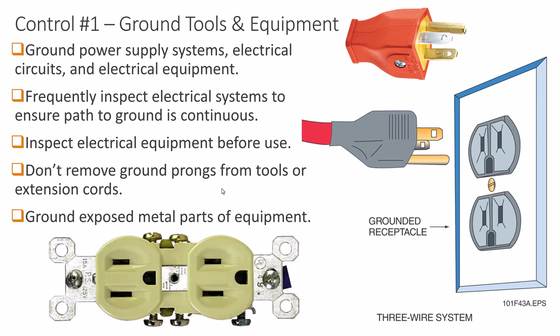You see on this electrical outlet here on the bottom, a real picture of one, how the hot wire is a smaller slot, the shorter of the slots, and the longer of the two slots is the neutral wire. And so you see that reflected in the colors of the screws. The brass colored screws is where the hot wires get hooked up.